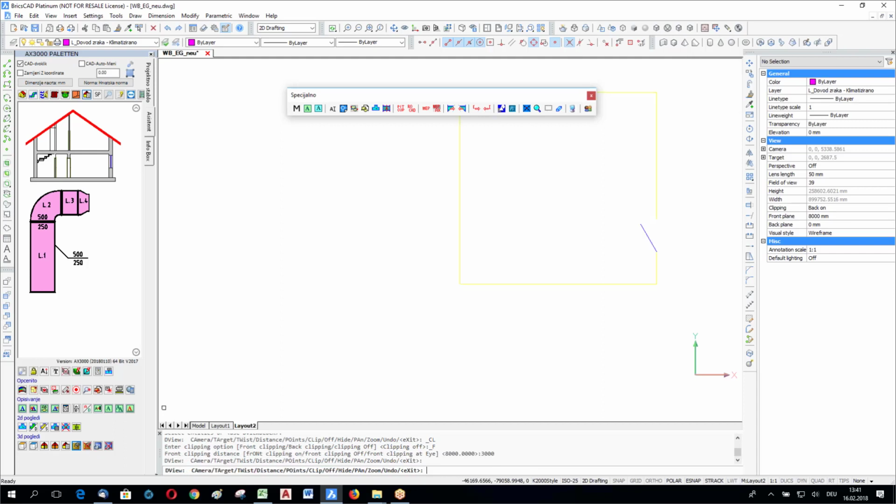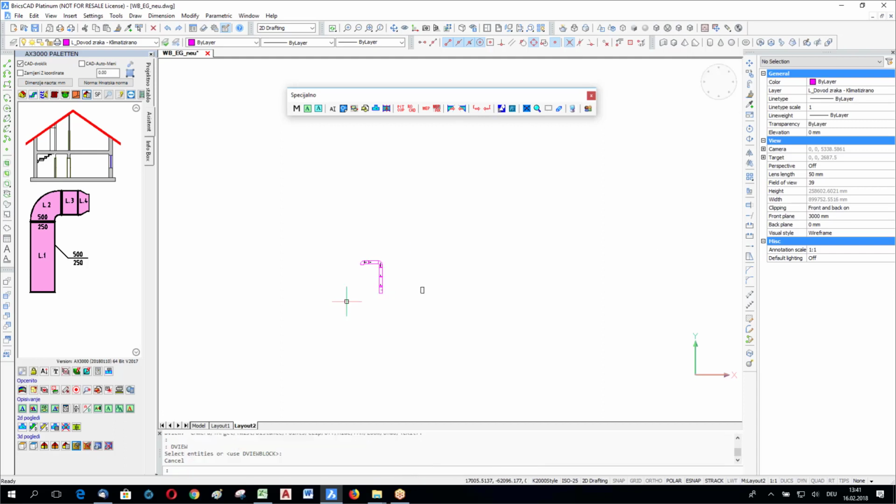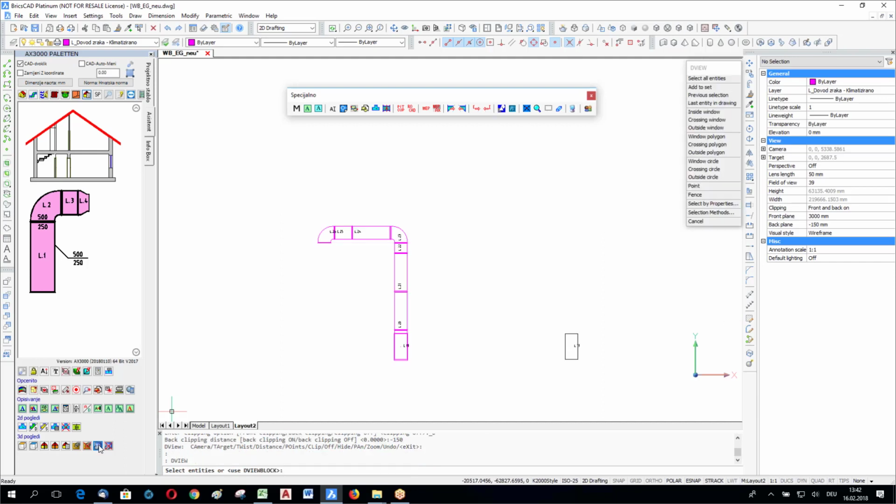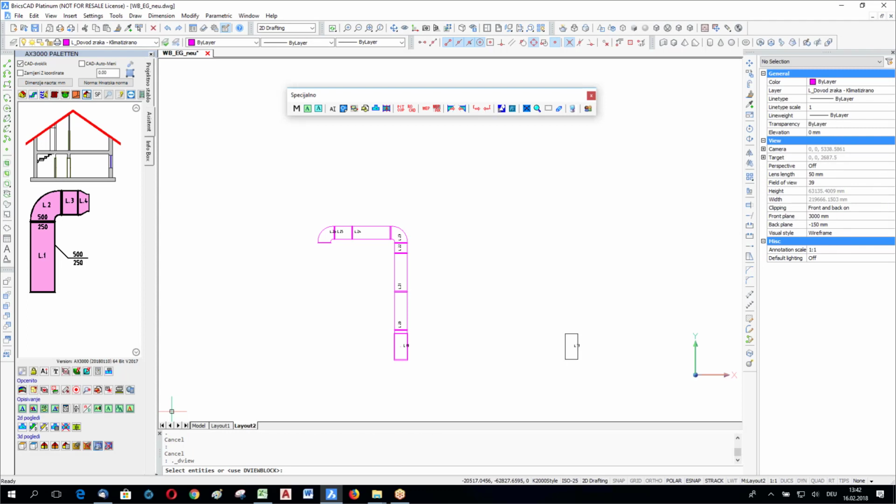Yes. So now I can only see elements between 8 meter as the upper level and 3 meter as the lower level. If I say now 0 up to 3, yes. If I say my lower is maybe minus 1 meter 50. Right, sorry, minus 1 meter 50 is one zero more, minus 1500. Upper one is